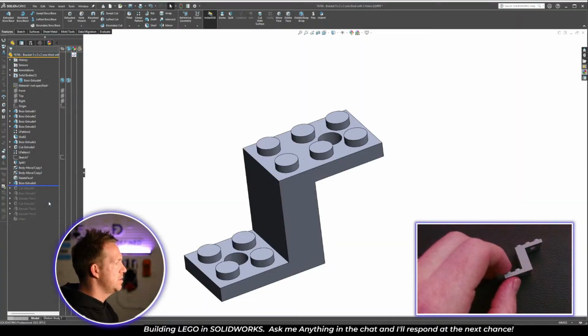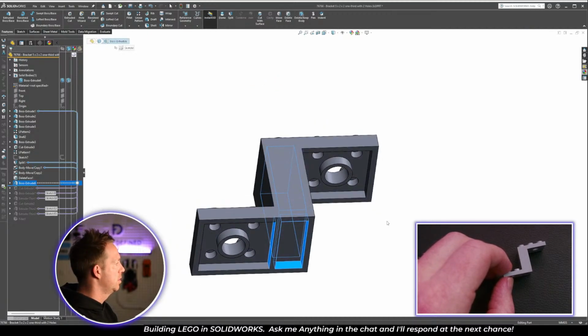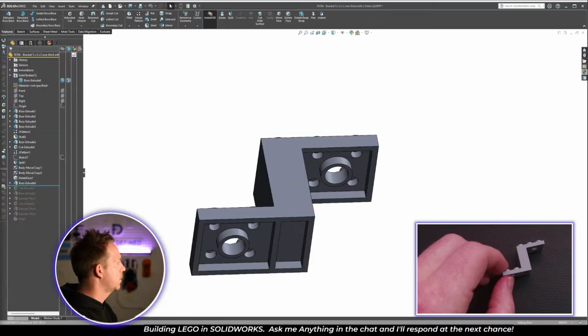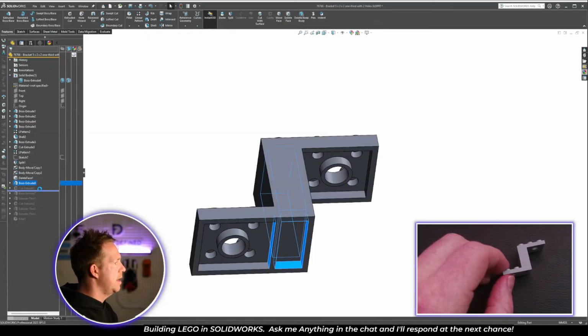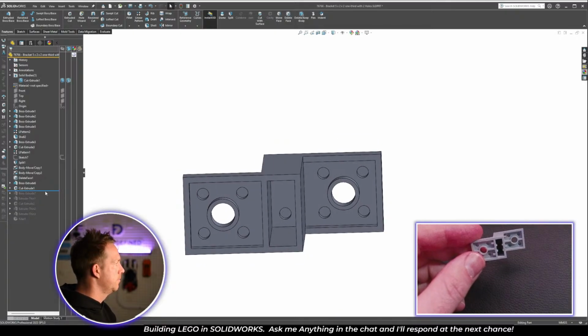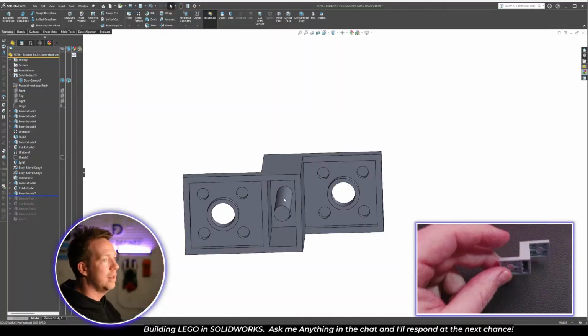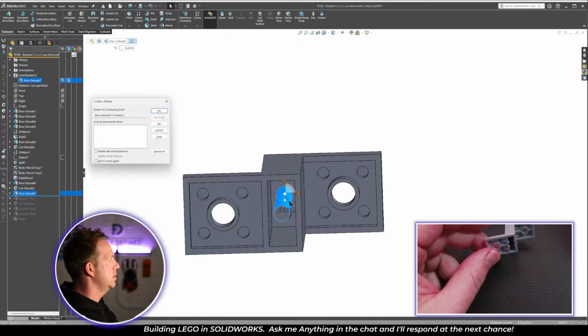All the features we've used last time should still work because that was an up to surface extrude. And let me just roll back down. So that cut goes through. That looks good. The other details, I can't see that boss in there. It's pretty dark. I think that gets left out. So I'm going to delete that feature.